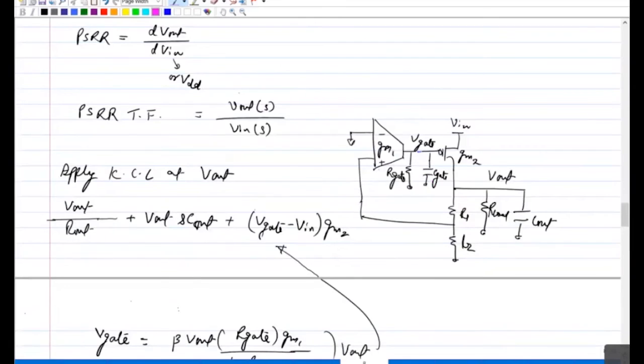So if you add the same amplitude, you take the DC component through feedback, like V gate DC will be based on your feedback, which is the required DC voltage to regulate the output, and take the AC component of Vin in the same value and couple them together.